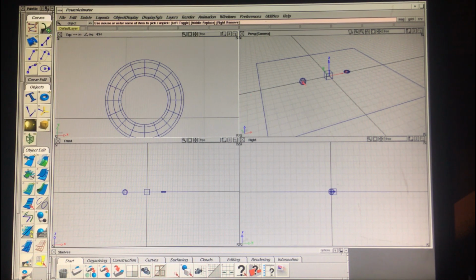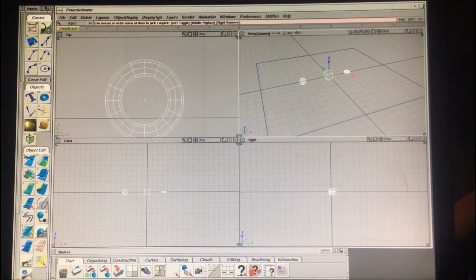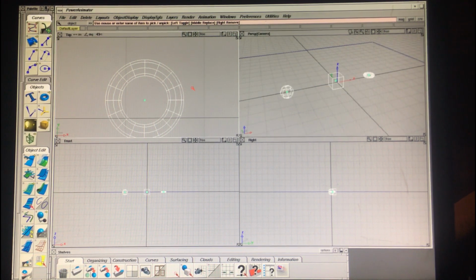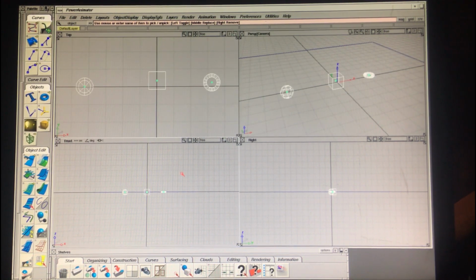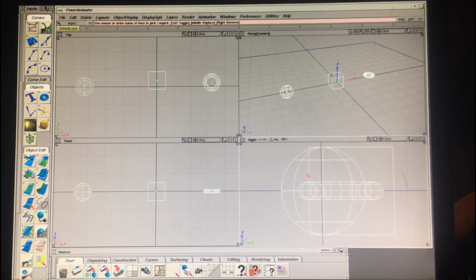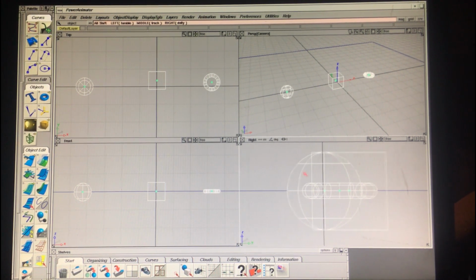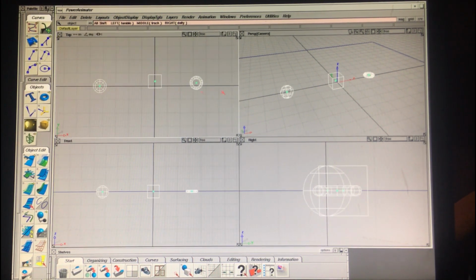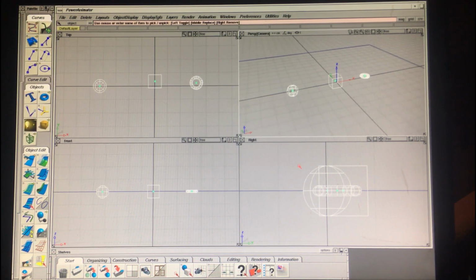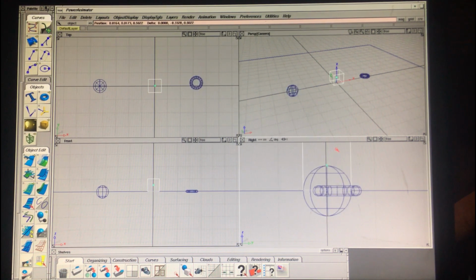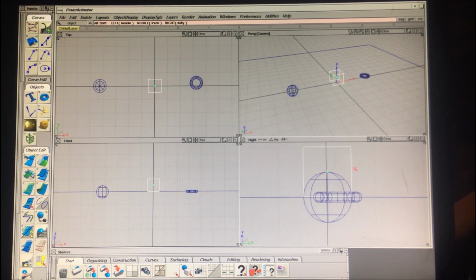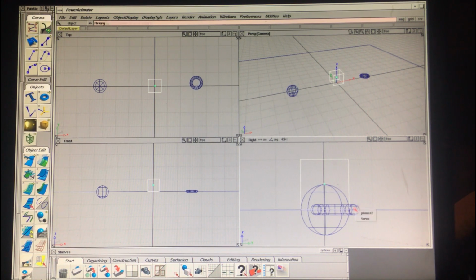All right, now let's select all three of these, and I'm going to hit that Alt+L up here in this view. See, and then I'll click this one, Alt+L. Click this one, Alt+L, click this one, Alt+L. And it allows me to basically zoom in on these items, but it's like pressing the F in Maya. And now Control Shift middle, and we'll use the move key, and we'll move these one at a time up on the floor here. I'll move this view down.